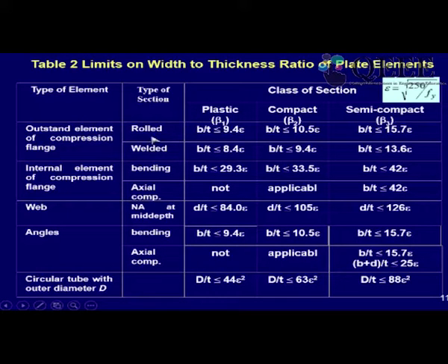So for different elements, whether the section is rolled or welded. Now again, why rolled or welded? Because rolled sections tend to have less residual stresses, whereas welded sections, because of welding, have high residual stresses. Hot rolled sections are heated and passed through a set of rollers to get the required I shape. That is called the rolling process, and then the section is allowed to cool in the air. That induces some internal stresses, which are called residual stresses. Those are relatively less in rolled sections, but for welded sections we take 3 plates and weld them together. When we weld, we heat a local area to a very high temperature, and then suddenly it cools. So it involves higher residual stresses.